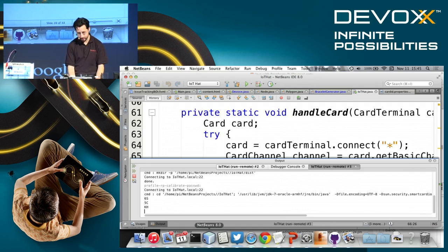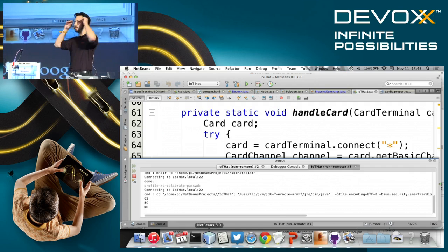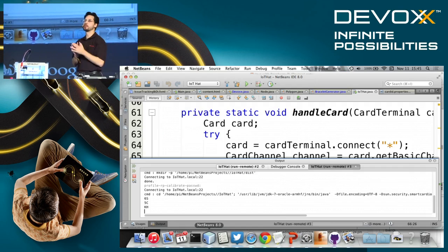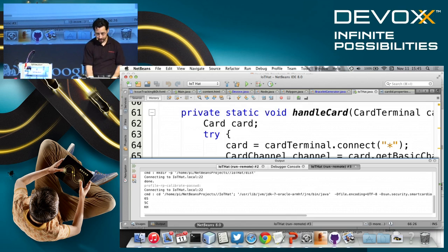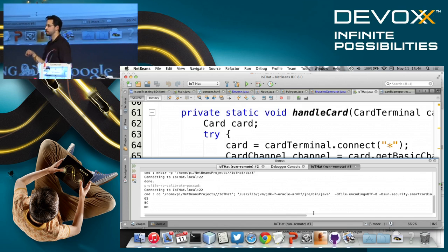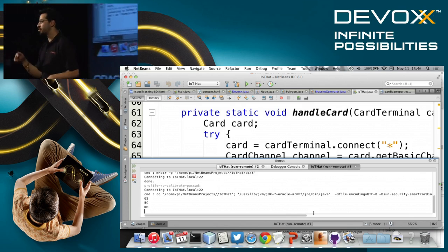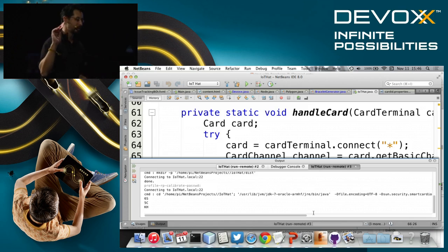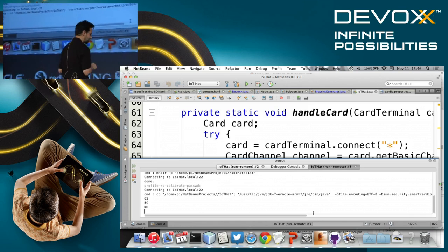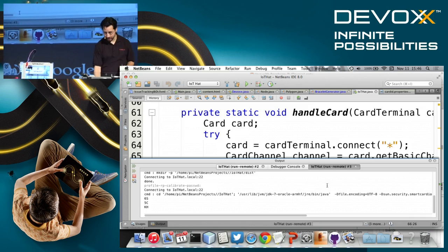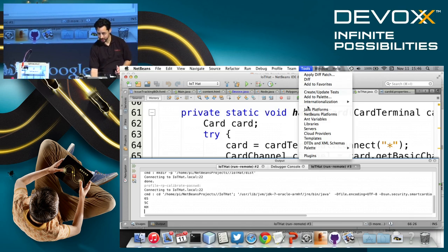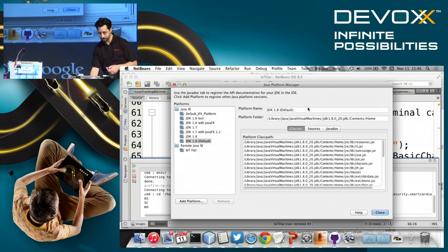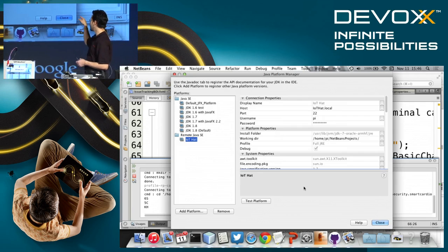The code here in NetBeans I was using, and I was doing this via remote deployment to the hat, which has a Wi-Fi connector in it as well. Somebody passed one of the cards back to the front, so I can demo this early. One of the questions I got on break was, how good is the NetBeans integration? And it's really easy to set up. All you need to do to set up the integration with your platform is create a new remote module and then give it the username and password on your Pi and the IP address.